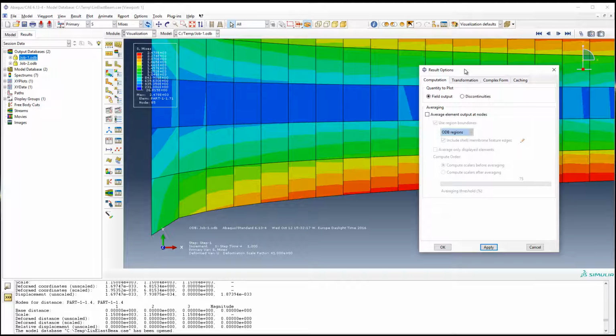But if you have the mass matrix and you interpolate the values such that you actually compute the unique nodal values, which is sort of the best averaging you can do, right? If you want to average the stress in this node, you have to look at all the connected nodes. This is what you do with the mass matrix.